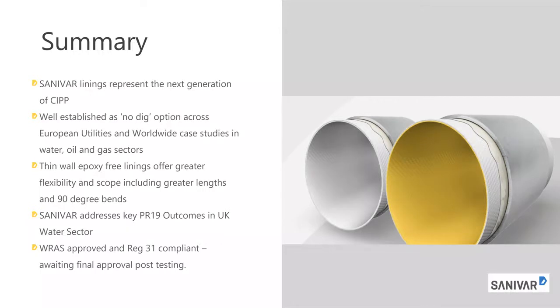Independently, Anglian Water have recently done a materials and contact test with Sanitube and have found no issues at all with it. We have a number of potable water mains lined up to refurbish, Regulation 31 approval pending, and realistically we would expect to know by the end of May whether we have any problems as a result of that testing regime.